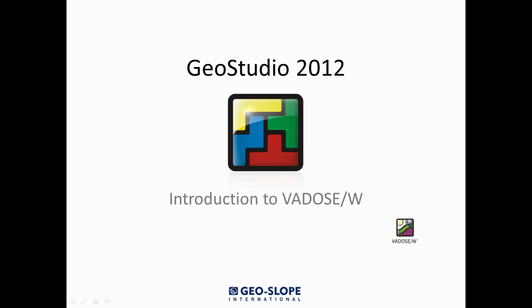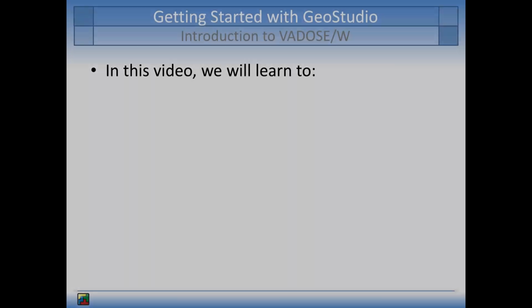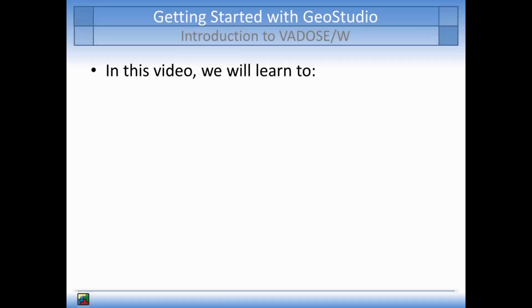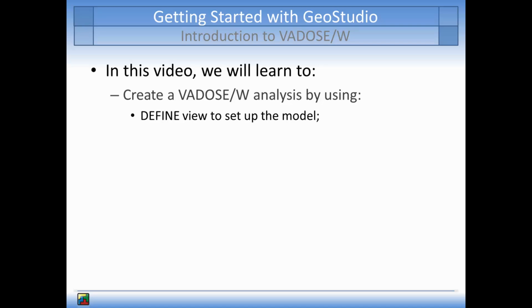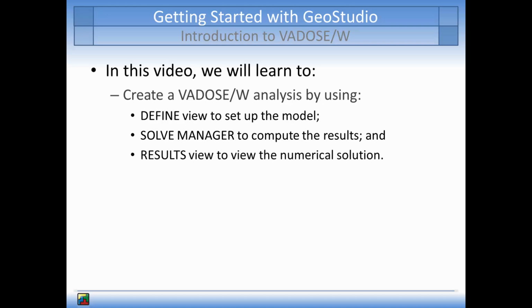So, if you are new to Vadose W and are not sure where to start, you have come to the right place. The main topics that will be covered in the tutorial will be how to create an analysis in Vadose W by using the Define view to set up the analysis, the Solve Manager to solve the numerical analysis, and the options available in Results view to gain a deeper understanding of the analysis.